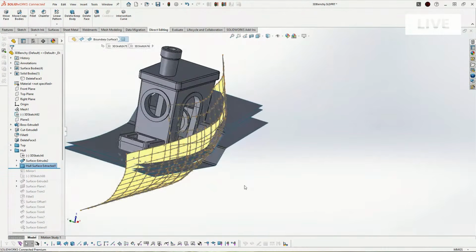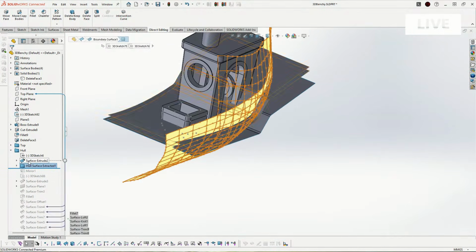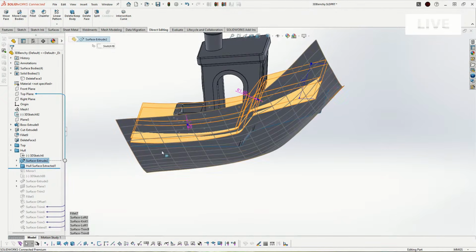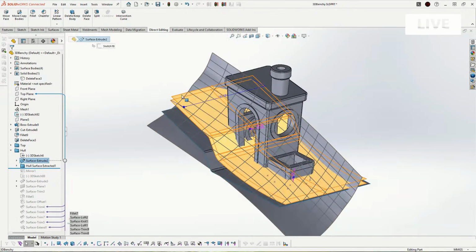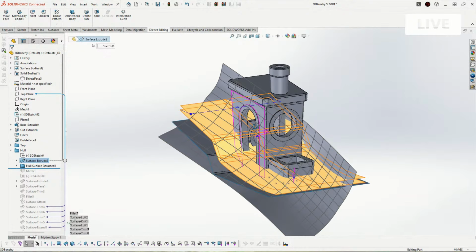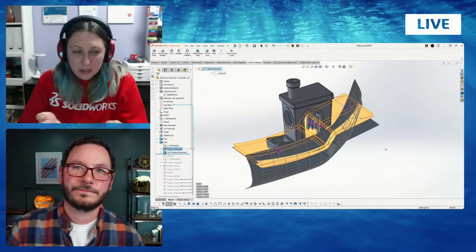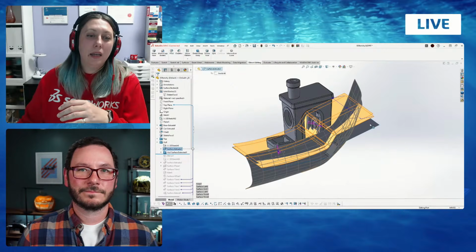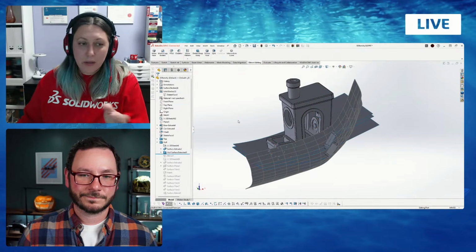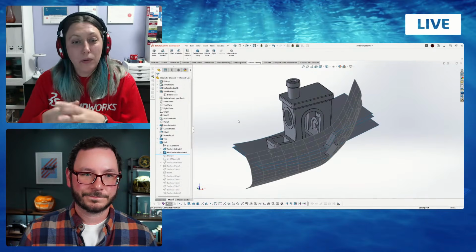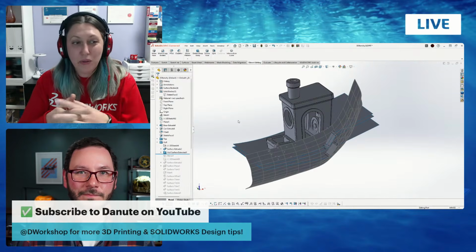And the other thing is here also you can see that I did build some of the faces with the help of 3D Sketch. I made the surface extrude for these two areas because it's much easier to draw it and extrude it instead of trying to convert that part. And this is the part with the planning. So split it into as many pieces as are comfortable to work with, and then go in, even if in separate files. Now, if I have to do it once again, I will for sure divide the benches into different files.